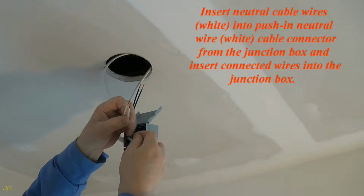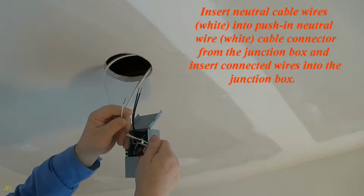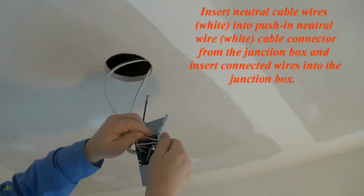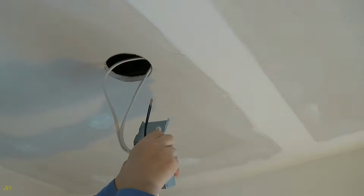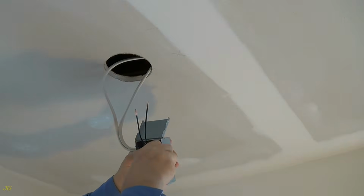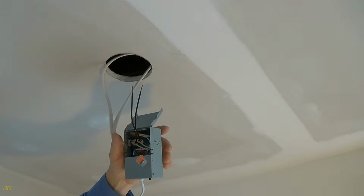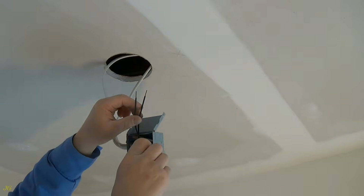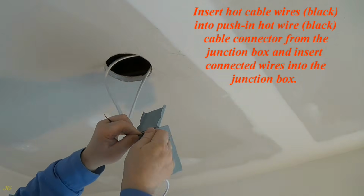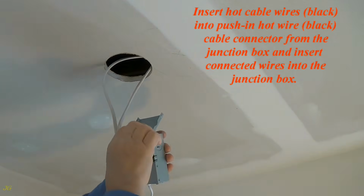Insert neutral cable wires, white, into the push-in neutral wire, white cable connector from the junction box, and insert connected wires into the junction box. Insert hot cable wires, black, into the push-in hot wire, black cable connector from the junction box, and insert connected wires into the junction box.